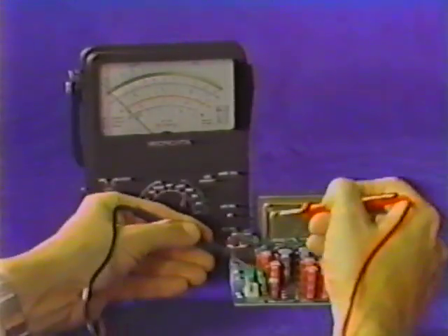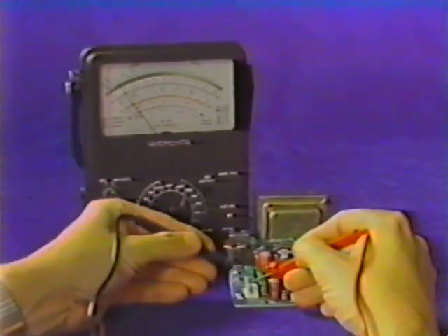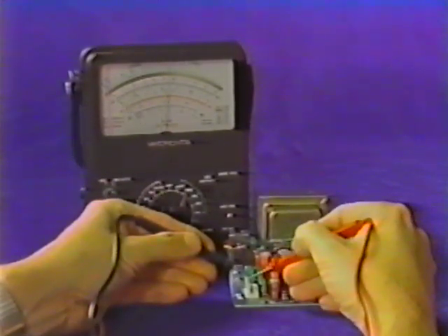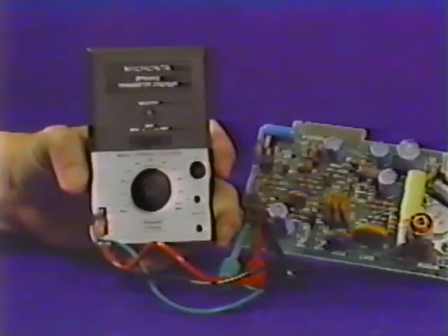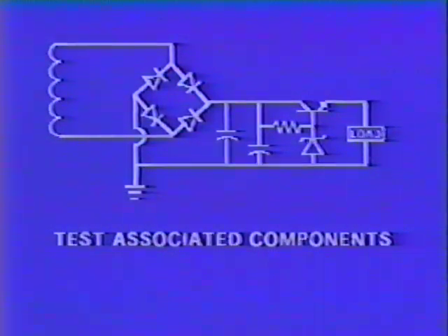When the defective component has been identified and replaced, perform continuity tests on the other supply components. It is not unusual for a shorted Zener to also cause the pass transistor to fail. If the transistor is not replaced, it will in turn cause the Zener to fail. Don't assume that just a single component is at fault.